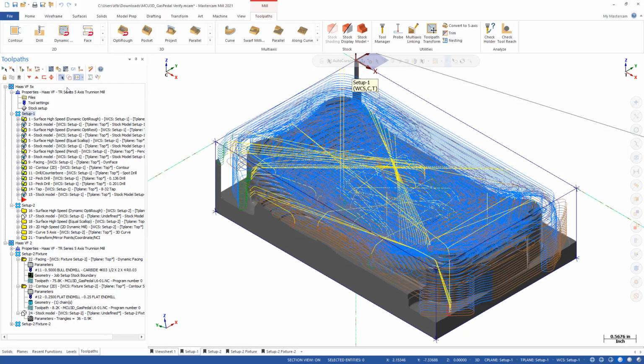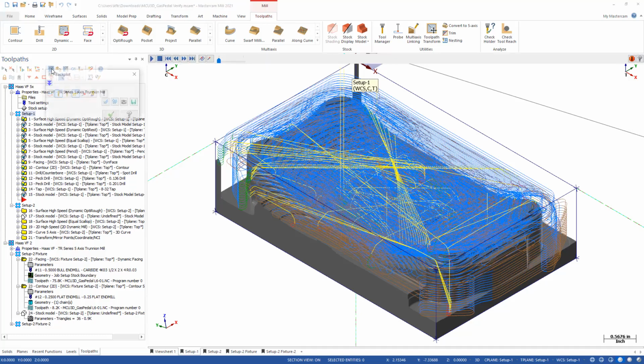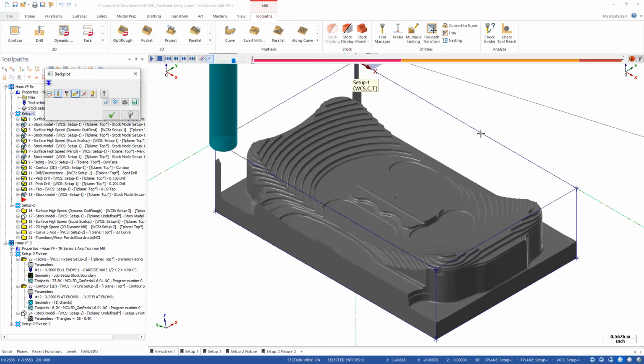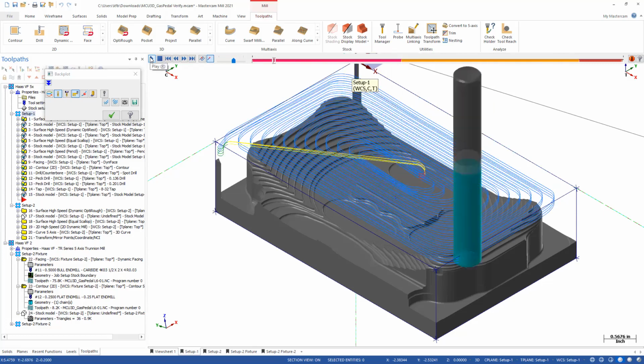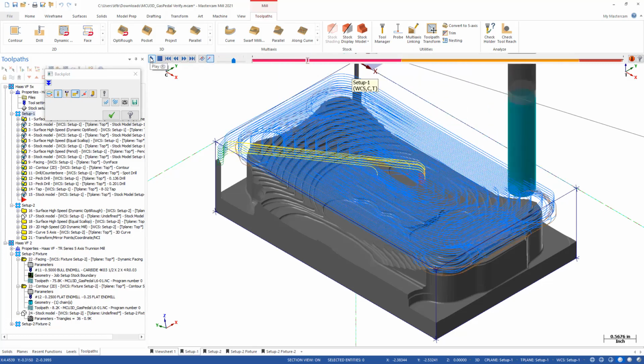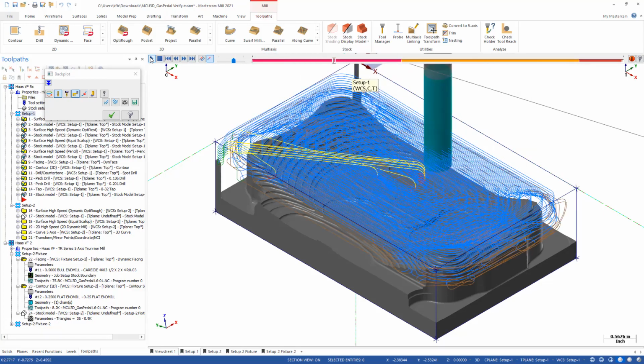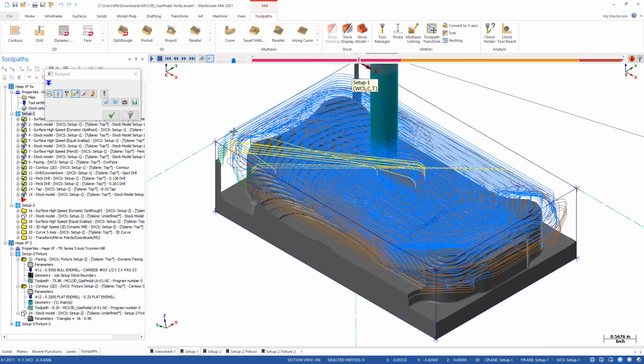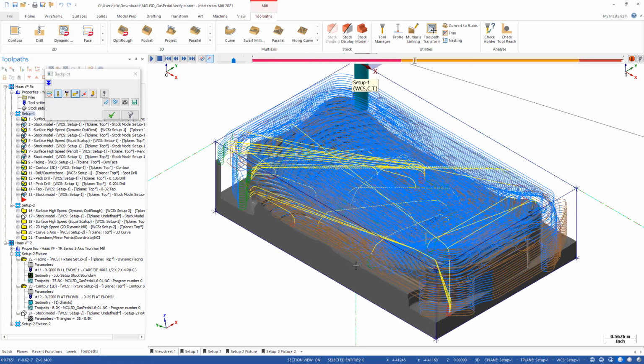At this point, with all of the toolpaths selected, we have a backplot option here, and as we saw earlier, this backplot brings up a backplot interface which is currently in our Mastercam session. So in other words, this backplot does not exit out of Mastercam. And it is a very quick way to go through and take a look at how this toolpath or toolpaths interact. And we're doing this just to review the various toolpath motion with this part before we look at it in the simulator.